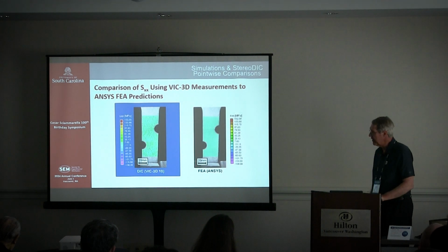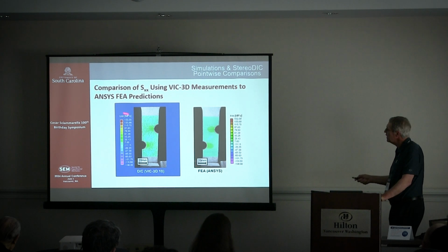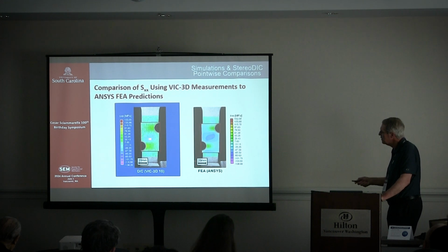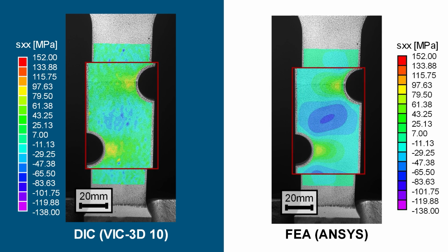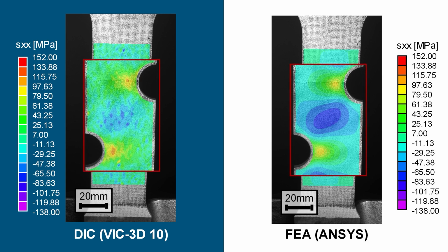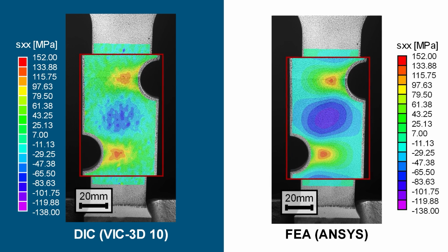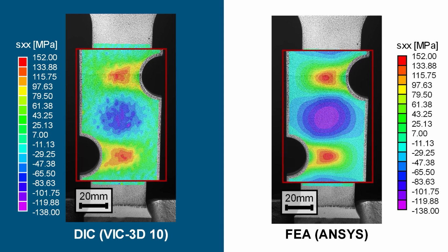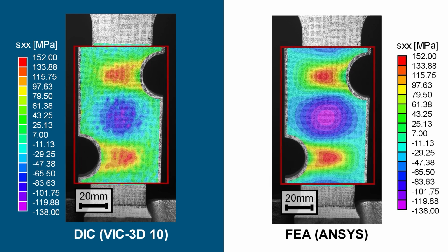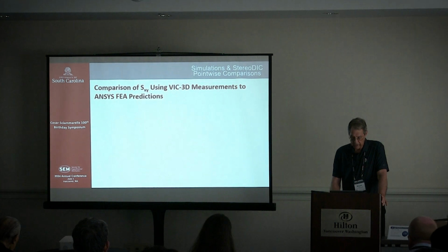This is what it looks like for the transverse stress. This one actually was not quite, because the stresses are fairly low, 150, but if you look carefully, this field here is not as well developed if you use the data. At least it doesn't look like. Later on, it becomes much more similar. But again, the strain differences are small everywhere. So the noise in the data is clearly visible in the stress field that you're calculating. As it gets further in, these become more clearly similar throughout. And the difference is, of course, you're multiplying by a large modulus.